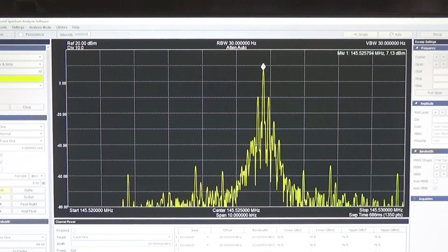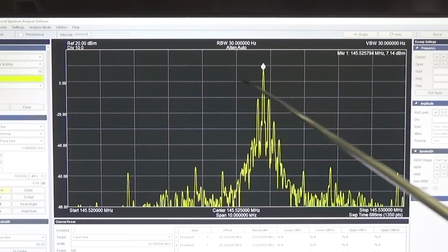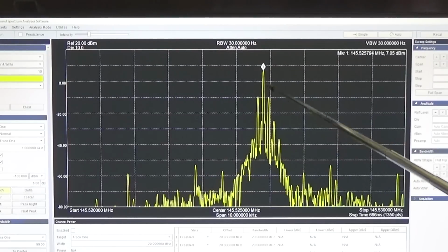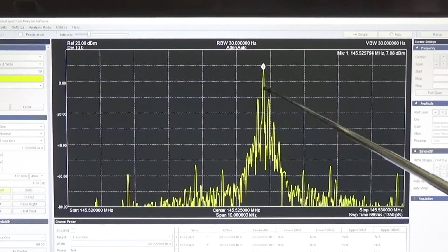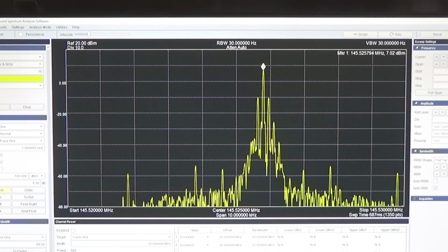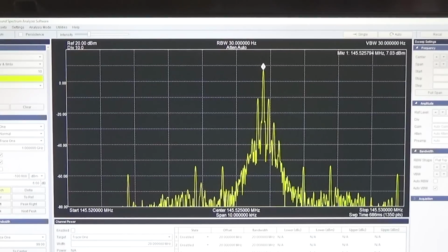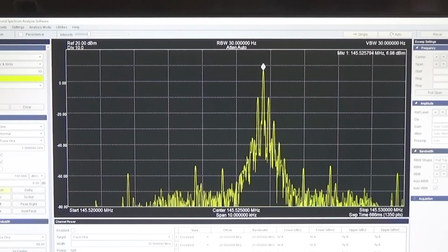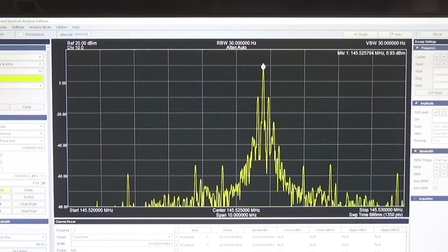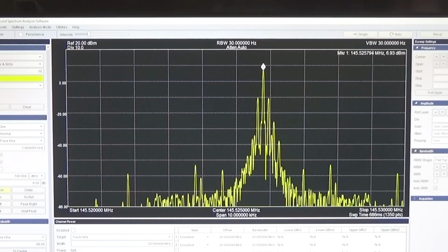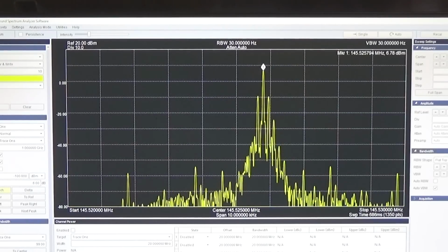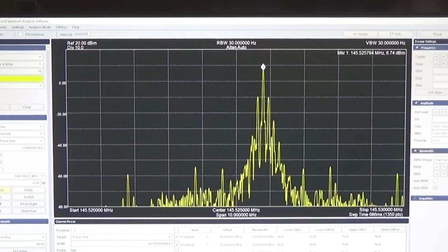Again, yeah, so it was already moving a little bit. So the reference oscillator is getting more warm, and so it is drifting in the right direction. Anyways, so we know that a lot of internal circuits are fine, otherwise we would not get this carrier. So therefore, let's have a deeper look into our radio.